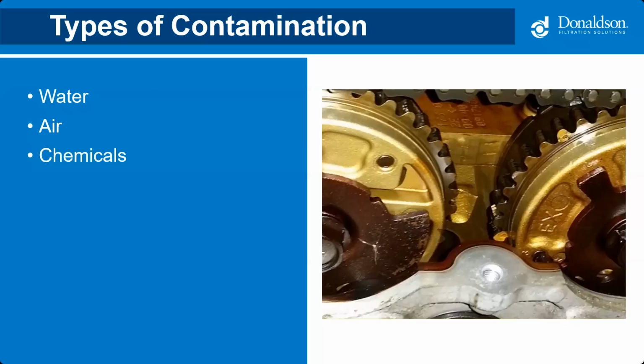Chemical contamination can arise when hydraulic fluid begins to degrade or oxidize and break down. It can also happen if different hydraulic fluid types are mixed. Incompatible additives may have unwanted chemical reactions, and chemical contamination is a primary reason to change your hydraulic fluid regularly.